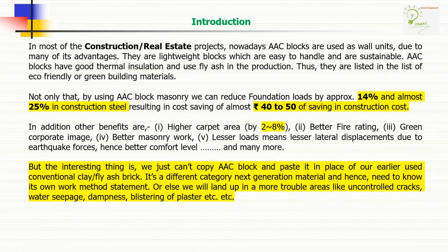But the interesting thing is, we just can't copy an AAC block and paste it in place of our earlier used conventional clay or fly ash brick. It is a different category, next generation material, and hence we need to know its own work method statement, or else we will land up in more troubled areas like uncontrolled cracks, water seepages, dampness, blistering of plaster, etc.